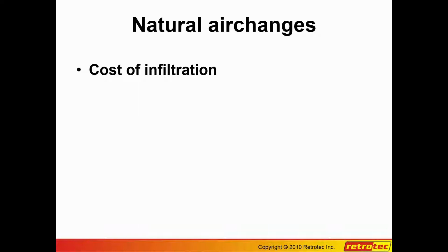So I'm going to move along here to natural air change rate. Let's drag the software up again and try to get an idea what the natural air change rate is. Remember earlier that we took the air change rate at 50 pascals and we divided it by 20, and we got 10 CFM. 200 CFM at 50, 10 CFM under some kind of natural conditions. That's just the easy way, or the rule of thumb way, to convert flow at 50 to natural flow rates. So that rule of thumb gave us about 10 CFM.